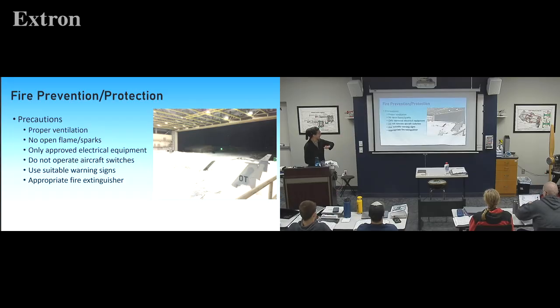Hopefully you wouldn't anyway. Anywhere near an aircraft. Make sure you have an appropriate fire extinguisher, which around aircraft, what would that be? CO2. Yep. Because any other, like a dry chem, is going to be corrosive.